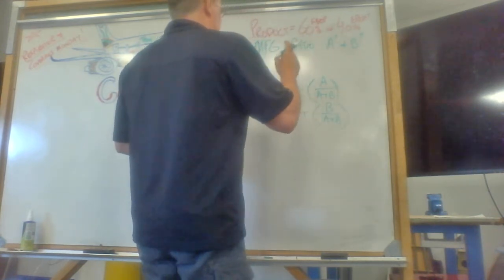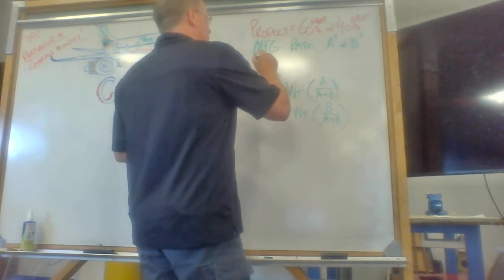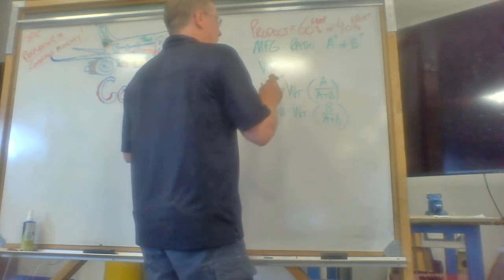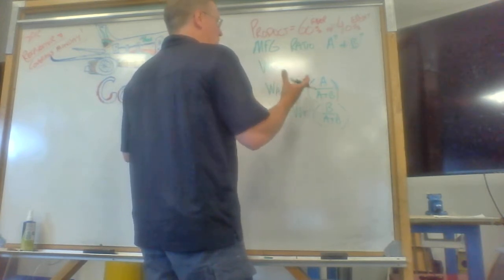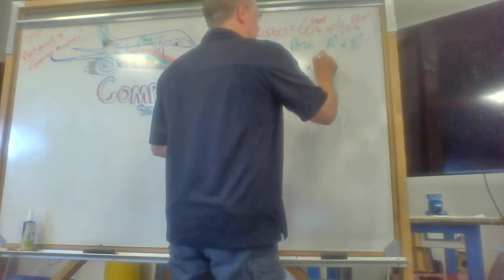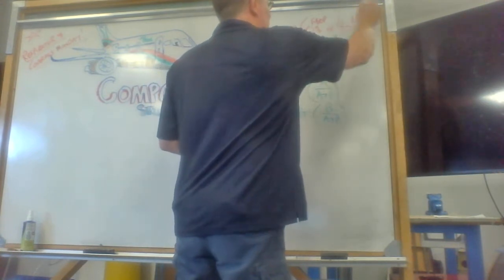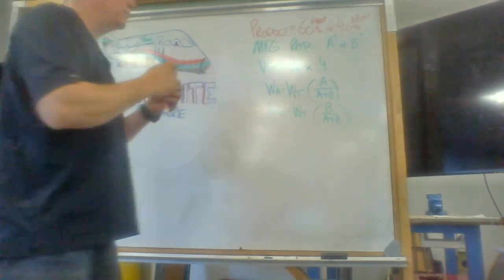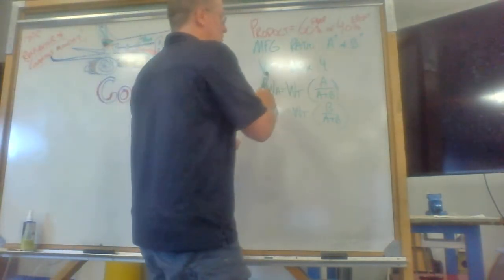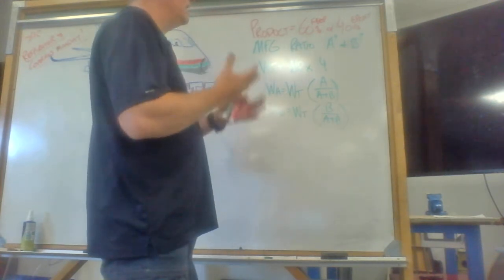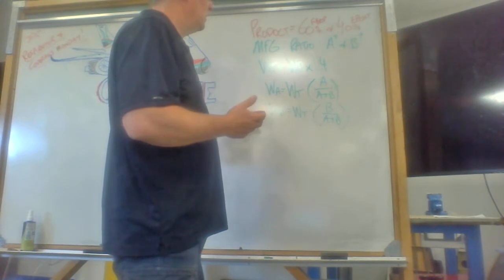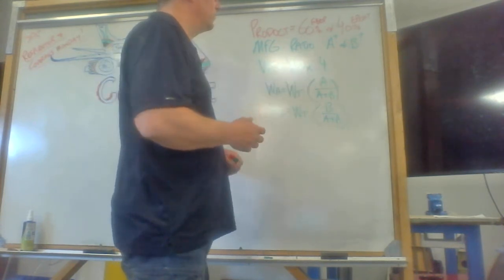But always remember that if they tell you the product weight, well, to find the total weight of epoxy, which is what we need to do, we're going to use the weight of the product, and we're going to multiply that by 0.4 because there it is there. The product is 40% epoxy, so that 40% epoxy represents the total weight of the epoxy in the mix, and we need to know that in order to find the parts based on the manufacturer's ratio.